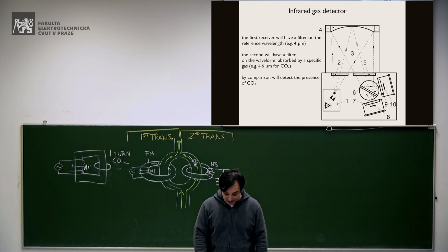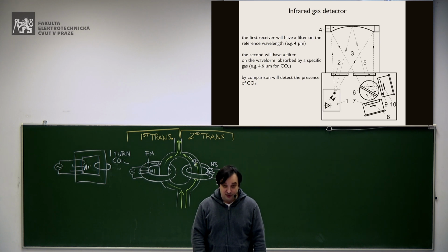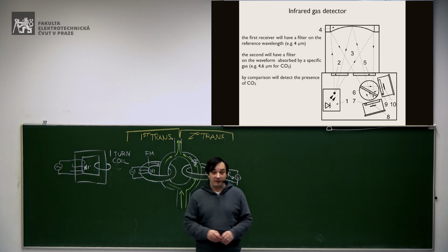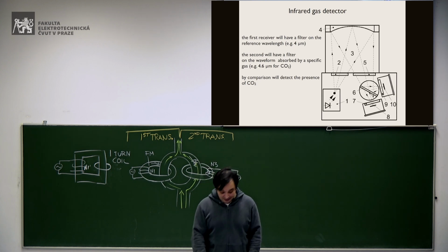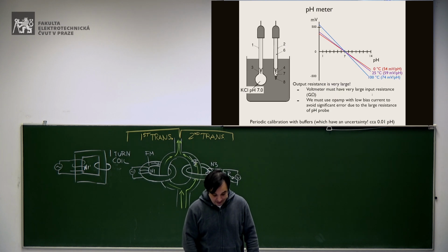So you always take the comparison between these two wavelengths. One which is absorbed by the gas that you want to measure, and the other which in fact is not, okay?